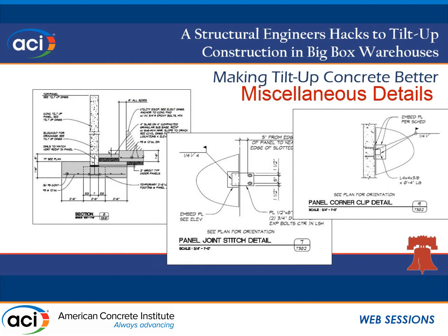It's just a couple of embeds and an angle that gets welded together. It's not a structural detail. Like, you're not trying to transfer force across the joint. You're just trying to keep the panels together, because as they try to move out, it really destroys the caulk joint, as opposed to side-by-side panels going to behave kind of together.